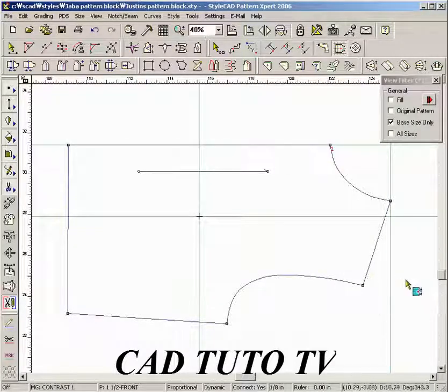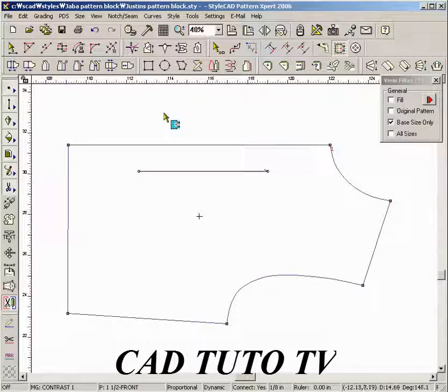In order to delete guidelines, select them with the Control plus Tab keys and press the Delete key. The Two-point guideline tool creates a guideline that goes through 2 points. Press the Control key and left-click the ruler area. Then, drag from point A to point B to make a guideline connecting the 2 points. In order to move a guideline, select the guideline, enter the distance, and drag it.